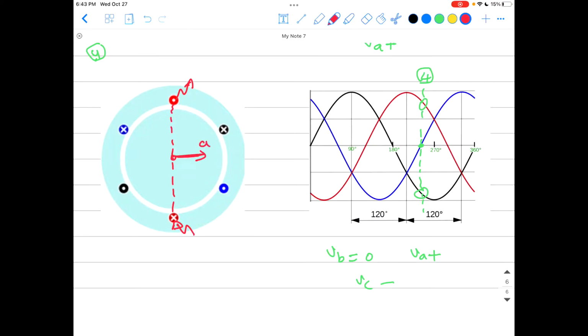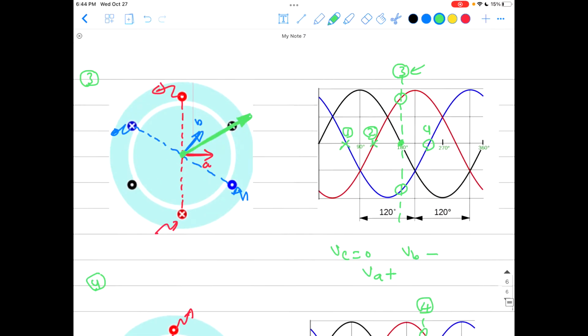That's coming from A. From C, which is the black one here, it's negative. That means the current goes into the dot, coming out of the cross. So the magnetic field of it will be perpendicular to it, but go in this direction, using again the right hand rule. If you take the resultant of those two fluxes, it will give you a direction here. That is the resultant of them. Okay, and here I'm pausing, and let's look back from the starting one.